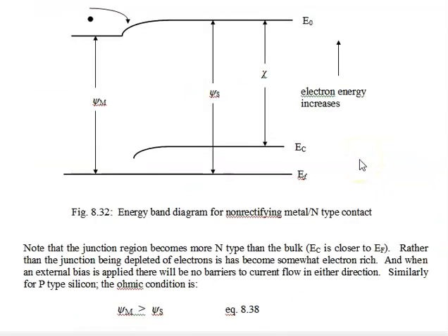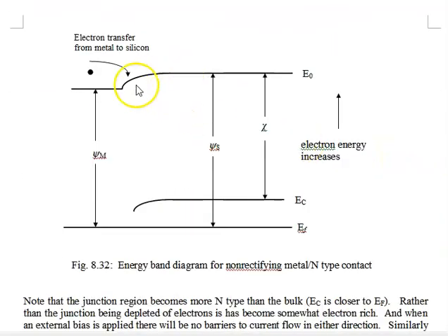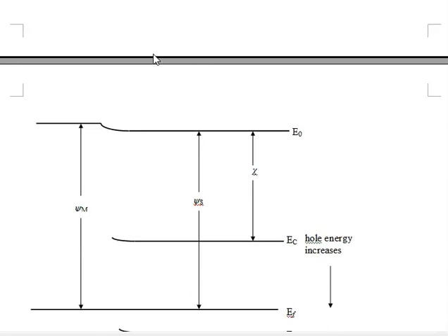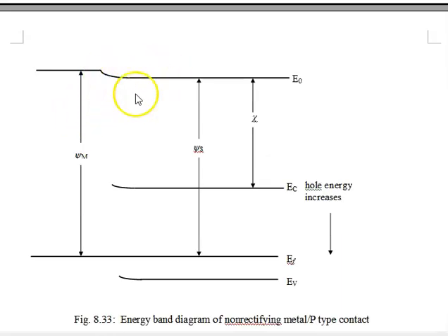And that is really the rationale behind non-rectifying junctions. So we'll start, this is for N-type. Now here, notice we said always N-type, always bends up. Well, that's for rectifying. And rectifying is the most important part. If it's non-rectifying, it actually bends down, but we don't really consider that as an important case. And of course, you can imagine if it bends down in a non-rectifying for N-type, guess what it does for a P-type? I know you knew that. It bends up. Okay.